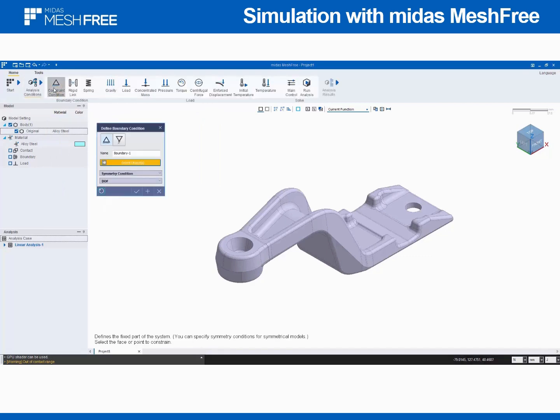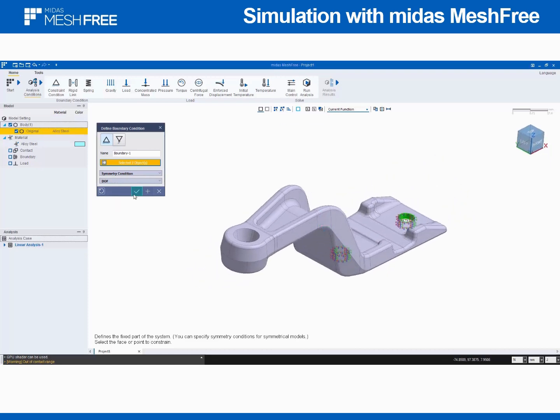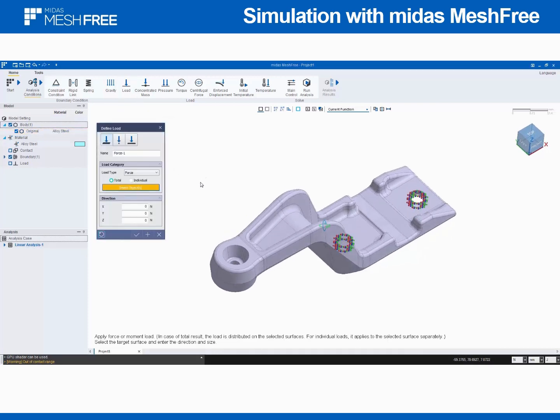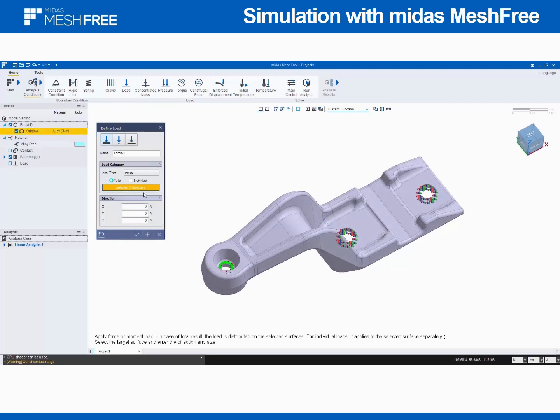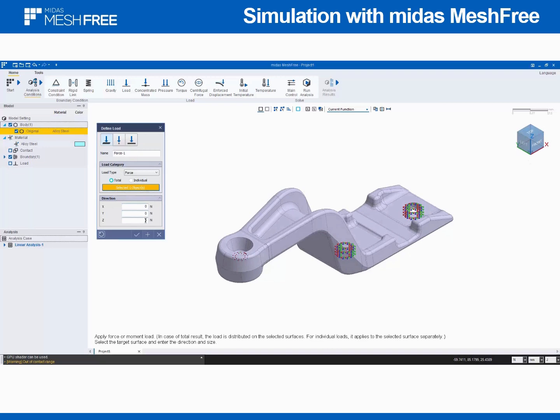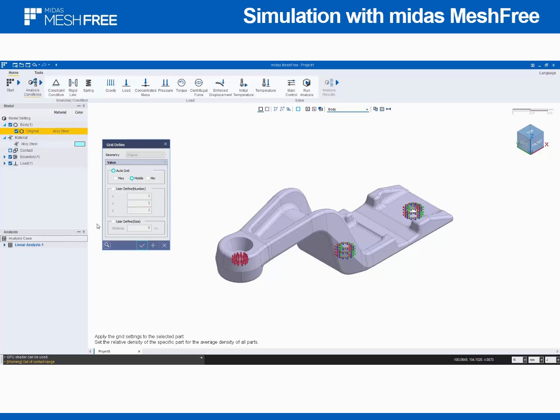So the next step is constraint condition. I'm selecting faces, and just to speed up selection, I'm clicking on the option which is called select tangent, and I'm applying load. So what we can see now is geometry. As I said, we cannot see voxels, we cannot see 2D facets. We are seeing geometry now. So I apply the load. I'm using cube as the reference for global axis.